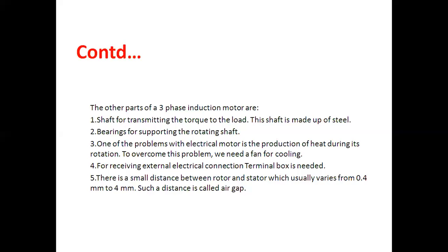To overcome this, a fan is there for cooling. For receiving the external electrical connection, a terminal box is needed. And there is a small distance between the rotor and stator, which generally varies from 0.4 to 4 millimeter. Such distance is called the air gap.